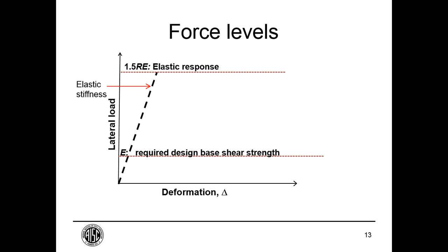1/6 to 1/12 of that MCE level acceleration. So this is the required strength, the required base shear strength of the structure. So the structure we know has to be within its design strength up to that level.